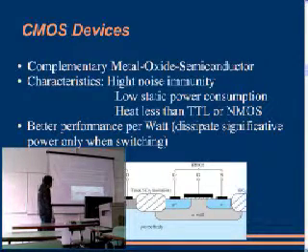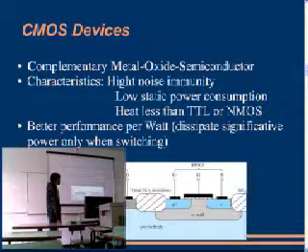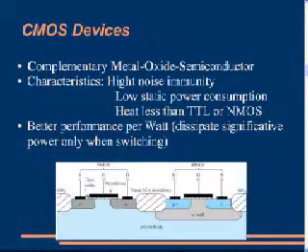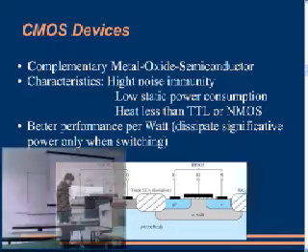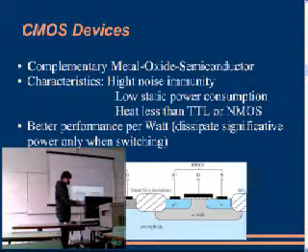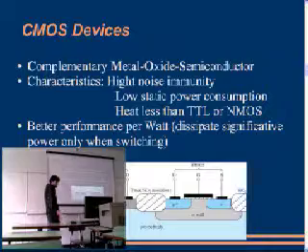The characteristics of this device are: high noise immunity in the static state and low static power consumption, because we just expend a good amount of current when we switch a MOSFET transistor, when we put it to high or low. When it is in a static state, it does not consume a lot of current. And this reflects a better performance per watt; it dissipates less power.